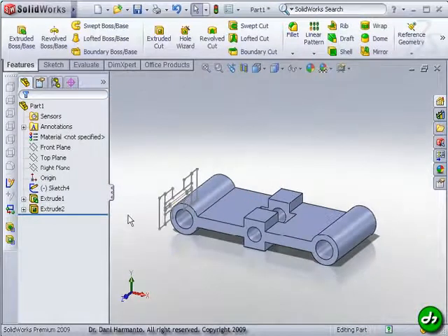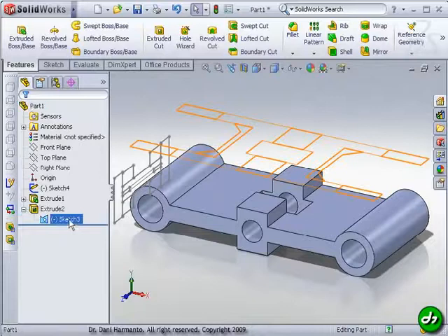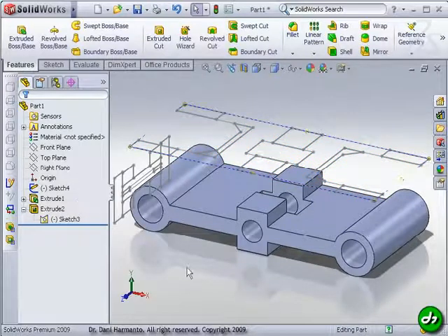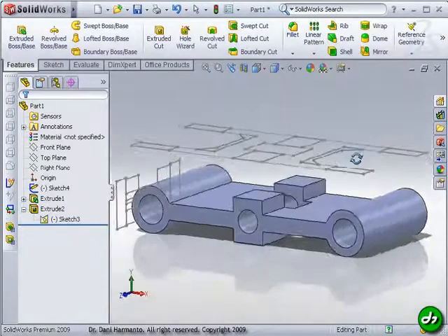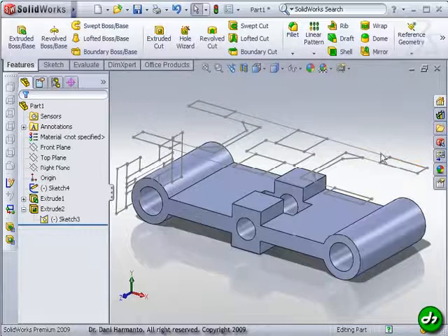That's the first one. Now you can see that the other sketch is gone, so just click in here, right click and click show, because we're going to use that again to cut for the outside one. I'm going to select a line through this edge, all of that, the outside edges, including on this line, everything, and then we're going to cut deep into that. I'm going to do it one by one,